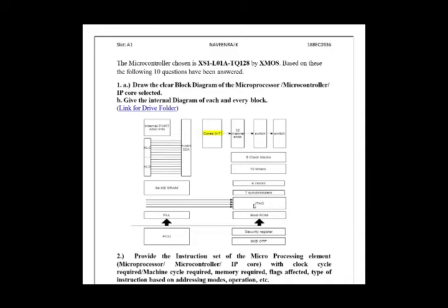The additional data in OTP is copied from the OTP to SRAM and executed first on the processor. So the first program executed is the boot program. The data from the OTP memory, along with some security register values, is transferred to the base of SRAM, and then the program is executed.